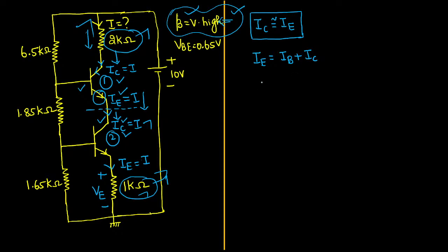So if I write that the emitter current and collector current are approximately equal, it clearly indicates that the base current is approximately what? Can you please tell me the answer? When these two currents are approximately equal, it means we are equating the base current to 0 ampere.